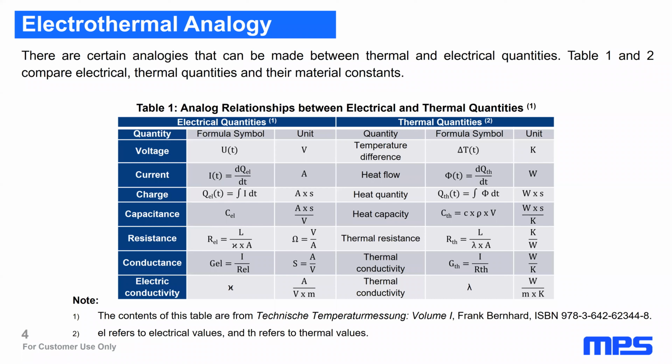For current, the heat flow. For charge, the heat quantity. Capacitance, the thermal capacity. Resistance, the thermal resistance. The conductance, thermal conductivity. So when you know how to calculate with currents and voltages, then you also know how to calculate with thermal quantities. It's just the same.